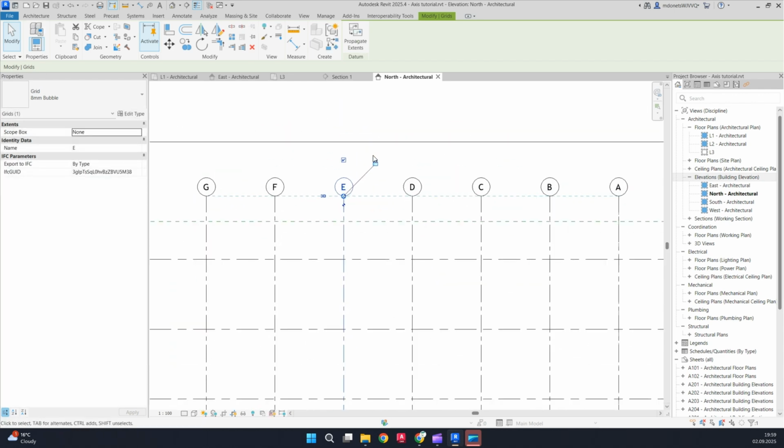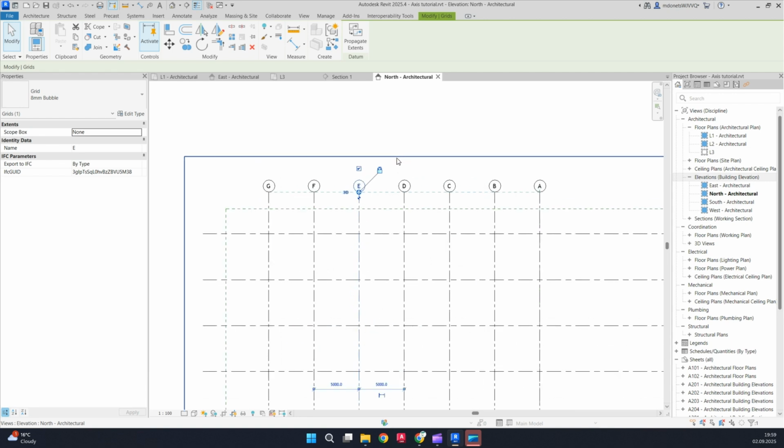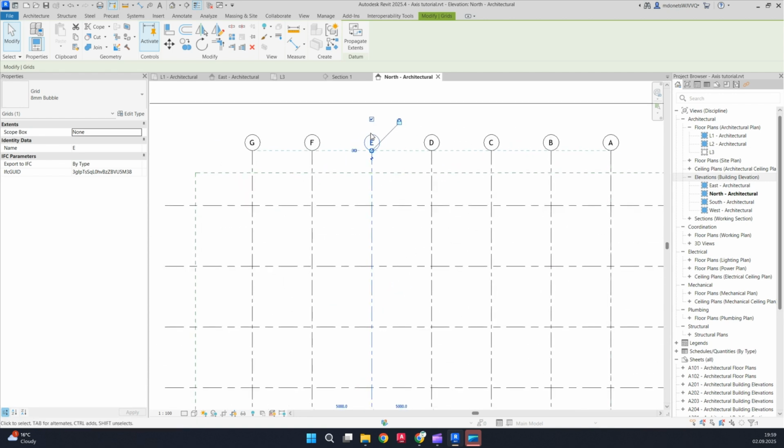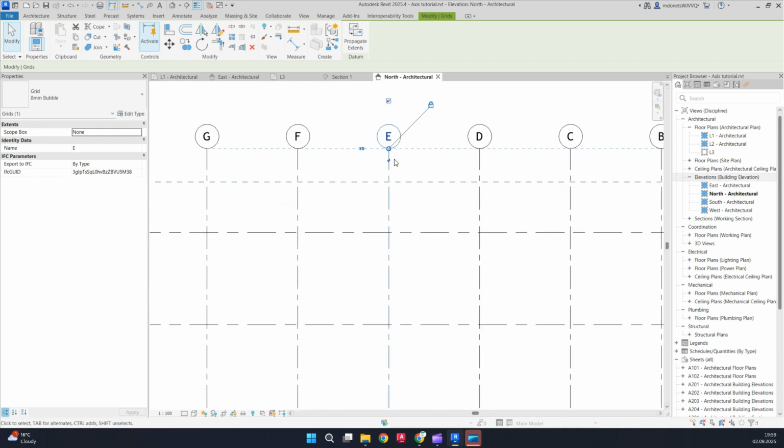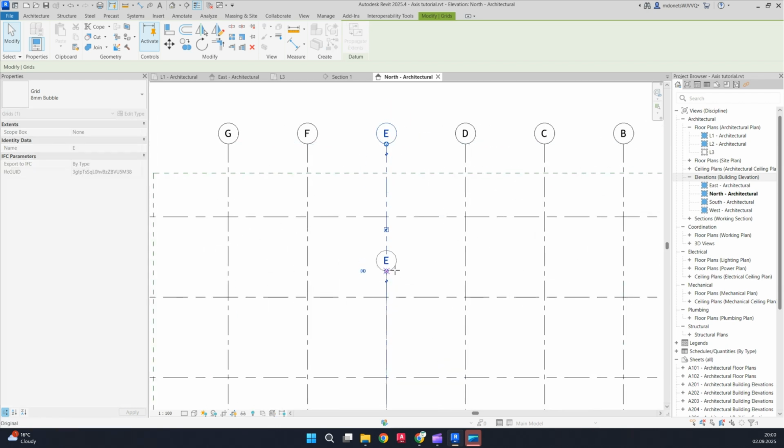If you need to drag one of the grids a bit further, or just want it not to be aligned, for example, one part of your building is smaller, you can just click this lock button, unlock it, and now it's not locked to others. If you need to get it back, just drag it slightly to the location of the others and it will pick the line and get locked back with the others.